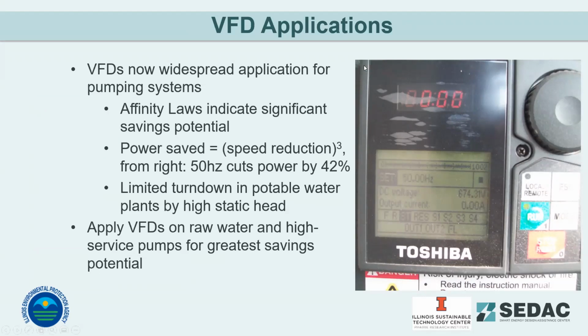So right now VFDs are widespread in pumping system applications. You always have to make sure you have the proper motors to use VFDs on. You can't just throw a VFD on anything. You've got to make sure your motor is efficient. Sometimes you may end up upgrading the motor and making sure your pump can handle that type of application.